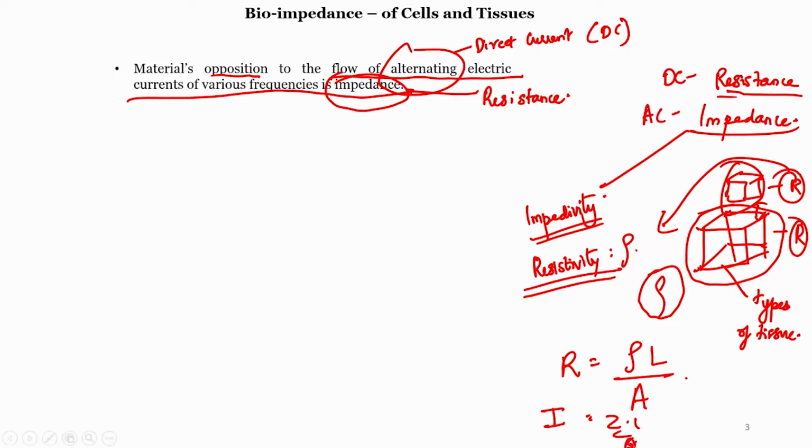We need to actually separate out the imaginary and real parts of the impedance and then do the impedivity calculation. Otherwise, by default impedivity will be a complex quantity, because as you know there is phase information involved, and capacitance, inductance effects will be there. So, there will be both the real and imaginary part in the impedance.